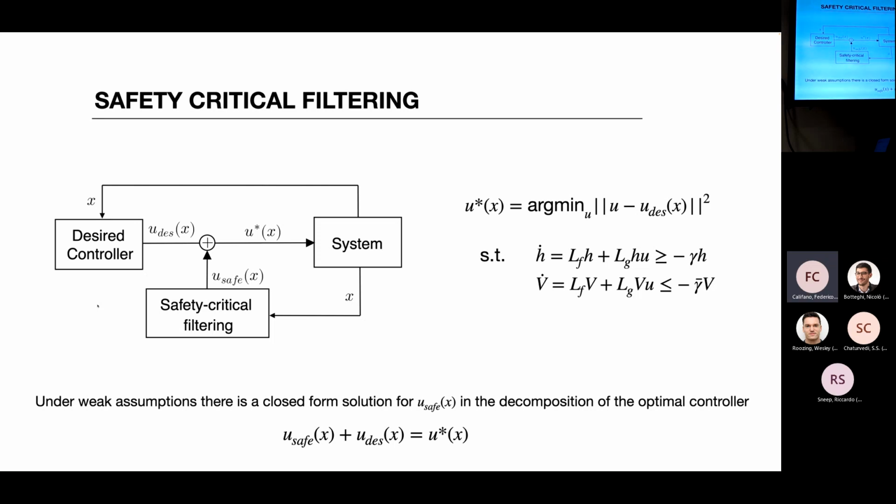Exactly, that's the problem of the relative degree. I would say that's the main problem. That is when we are in the mechanical domain and we have a torque controlled system, not a velocity controlled system, but a torque controlled system, then the relative degree of the system is 2. That is basically, the U does not enter the H dot.